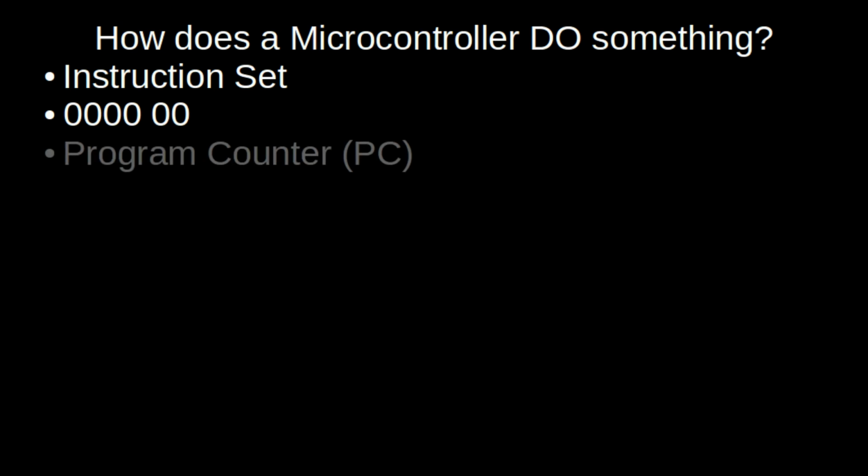All Atmel AVR microcontrollers use the same basic instruction set. The instruction set is referred to in the microcontroller by a binary number that is 16 bits long. While this sounds like there could be thousands of instructions, in reality, most of the instructions are encoded by the highest 6 bits, and the rest of the binary code deals with variations of the instruction for different registers and such. We will deal with registers shortly. This microcontroller keeps a list of the instructions you want it to do, the program, in part of its memory.